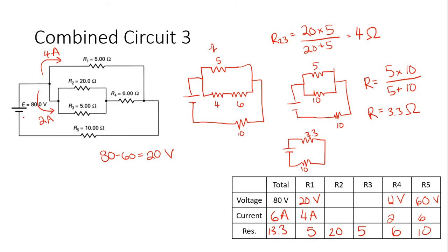I had 20 volts coming in here, right? The 20 volts we had there. I am going to use 12 of it here. So the leftover for this little R2, 3 parallel bank is 20 minus 12, 8 volts. And R2 will get 8 volts, and R3 will get 8 volts.